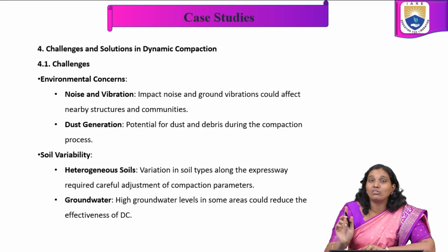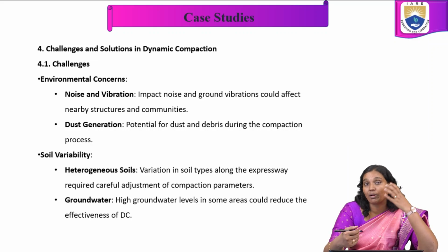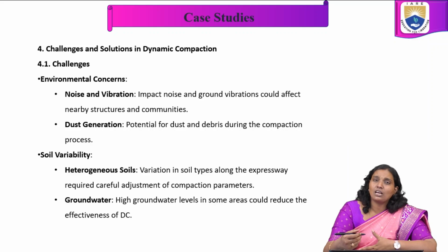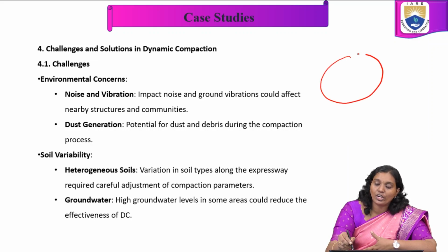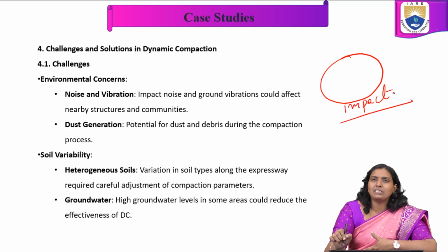We also have to check the nearby surroundings, what kind of weight we are taking, and from which height we are dropping it onto the soil. These are all the parameters we have to keep in mind at the time of dynamic compaction, because the surrounding areas are going to be impacted by these vibrations.